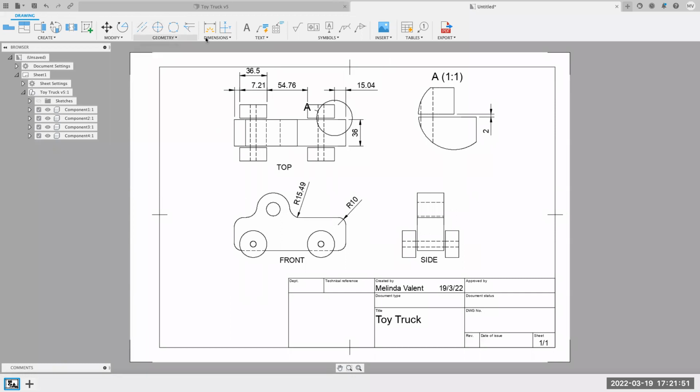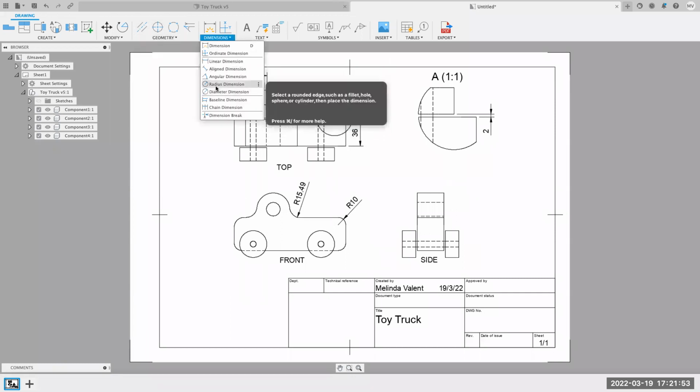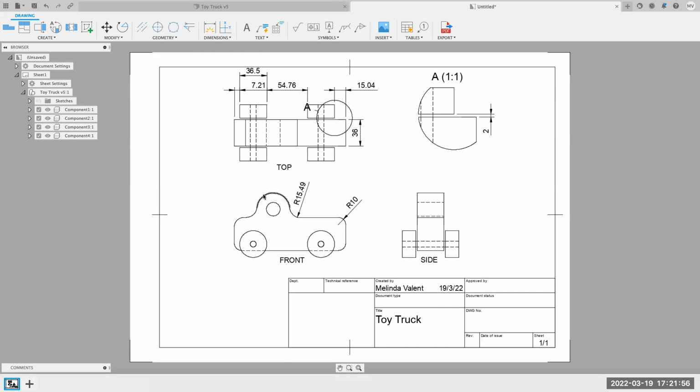Okay, so where it's not a full circle, radius is more appropriate, whereas if it's a full circle, diameter would be the best, most appropriate option. So here we go. I was pulling this out. Now, again, you can see here 36.5, I'm doubling up. I've got it up here. It's in effect redundant, and it's over dimensioning. So I can just remove that because it is unnecessary.